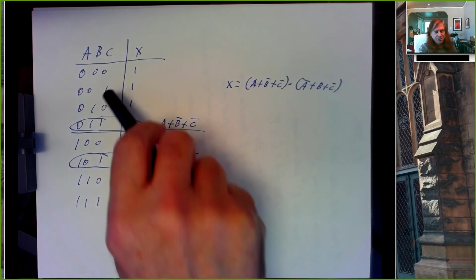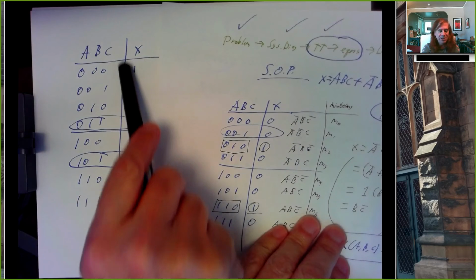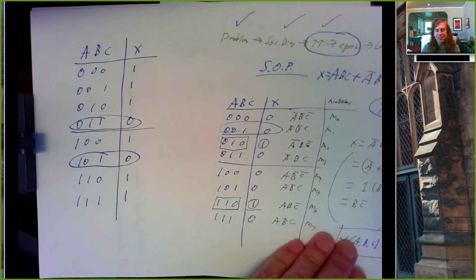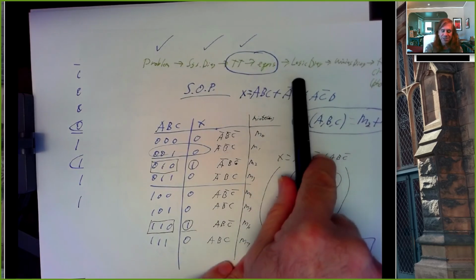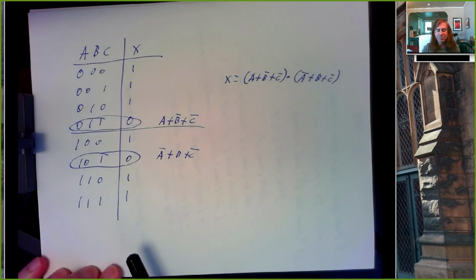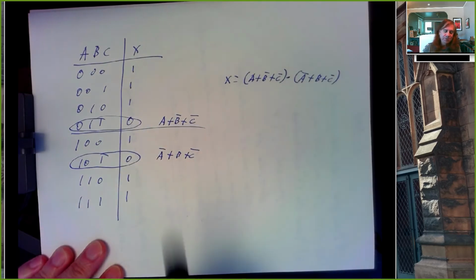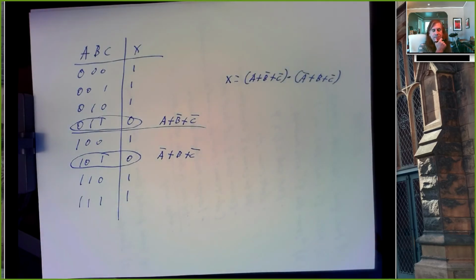And this truth table is fundamentally no different from this one. I mean, it looks peculiar because most of the outputs are 1s, but really it's just another truth table. And it's not going to affect how we go from equation to logic diagram and so on. But because there's mostly 1s, it may end up taking less hardware if we do this product of sums equation. Sorry for the background noise, but so this is basically just to make a smaller point when there's more ones than there are zeros.